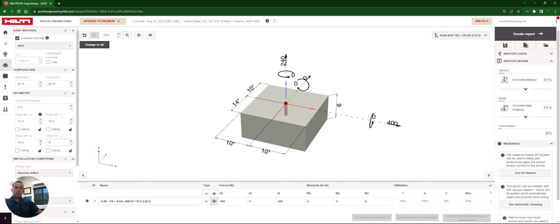And this I'll verify once I do the drawing. So basically, once I draw this in AutoCAD, I'm going to want to verify that around each bolt there's at least 10 inches before you hit the edge of the concrete. And that's important for concrete breakout. All right, so that looks good to me.